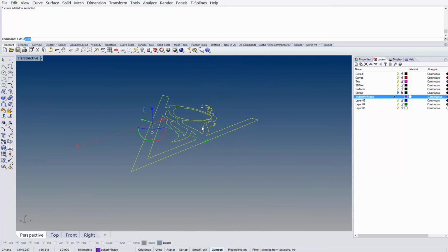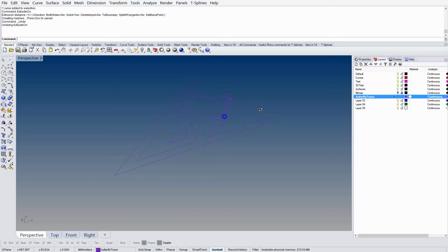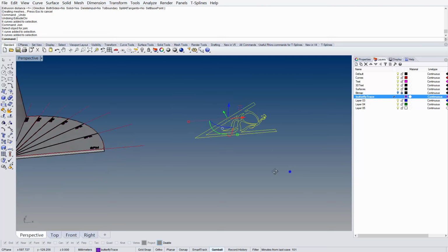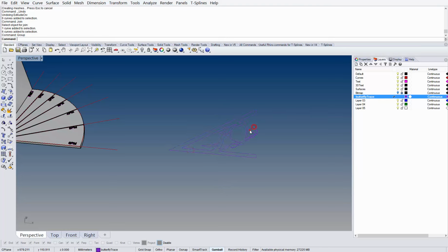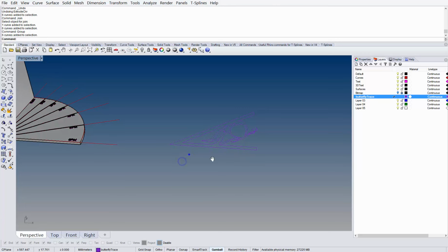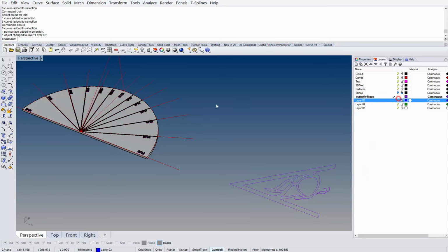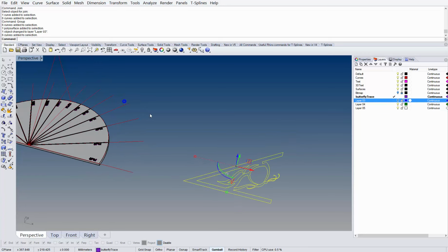I'm going to extrude the curve up, and it's solid. It looks pretty good. So before we extrude, let's select it all and type join again, just to make sure. I guess it's already joined. So we can select it all and type group as well. And so now this groups it all into one selection. We can go in and delete our original gnomon, or put it on another layer, for example, and turn that layer off. And now let's move this butterfly into position over there.